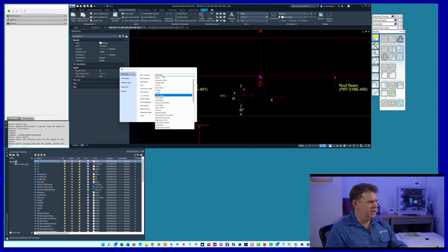Let's go again. Let's put a fillet side on this one side. 6. Let's put a stitch weld in here. Let's put in a 50 weld at a pitch of 300. We won't have a groove angle here, but we will have flat. We'll put a stagger in here, root gap 2. On the other side, we will put a, what do we want to put in there? A V butt weld.